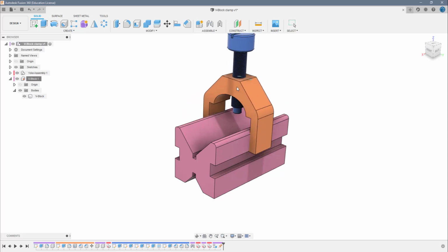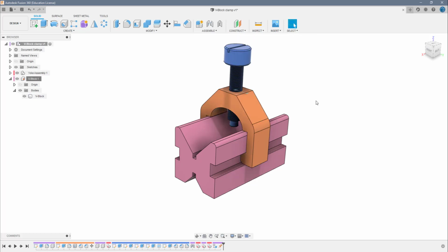This assembly that's connected here, anytime you move an assembly, it's going to jump away, and we can either capture the position we've moved it to, or we can set it to there. Now that these are components, we can start to apply these things called joints that allow you to make these move in the method they would in real life.